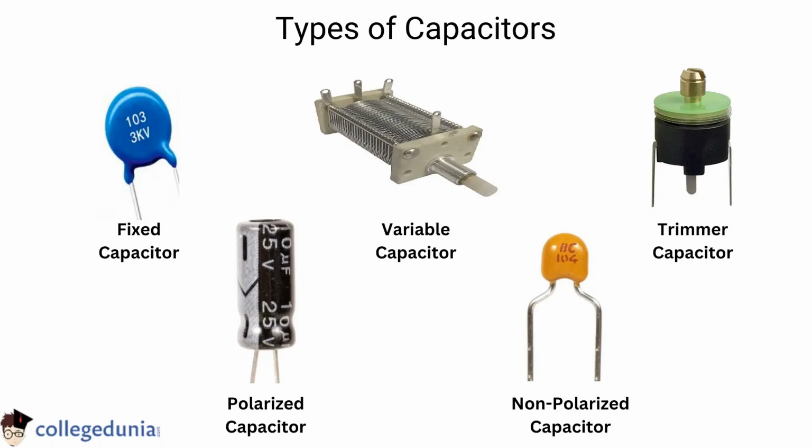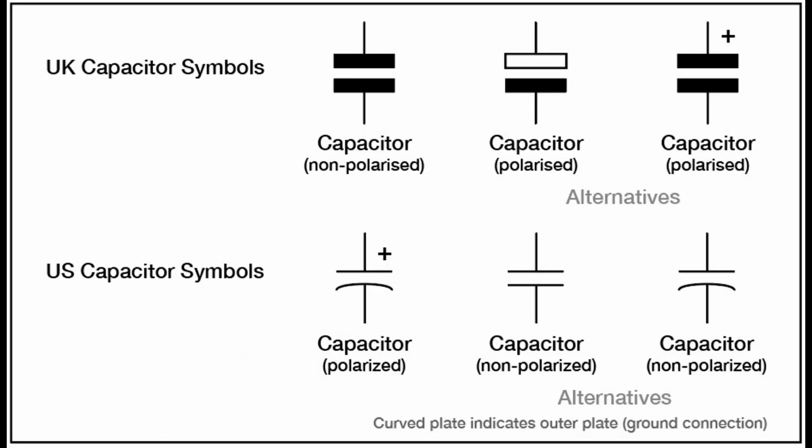Audio systems. Electrolytic capacitors are used in audio systems, such as amplifiers and speakers, to couple and decouple signals, filter out unwanted frequencies, and stabilize voltage levels. They contribute to improved sound quality, reduced distortion, and better performance in audio equipment. Motor drives and inverters. Electrolytic capacitors play a crucial role in motor drives and inverter circuits, which are used in various applications like industrial automation, electric vehicles, and renewable energy systems. They provide energy storage and help smooth out voltage and current fluctuations, ensuring stable operation of motors and power electronics.